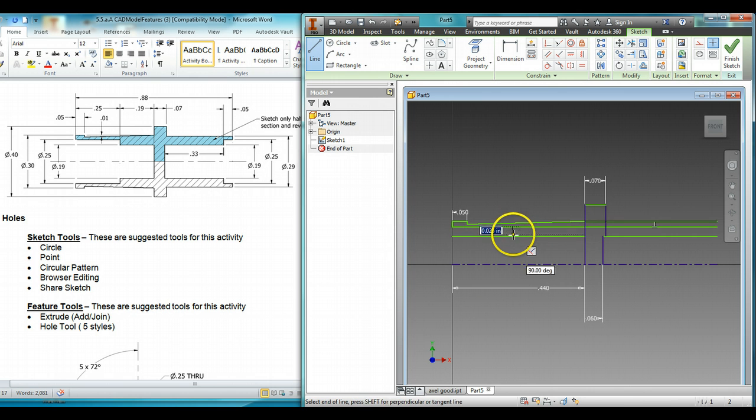Okay, so I have a feature which is 0.25 inches over at the 0.19 diameter mark. So I am going to locate a line right there. Then I'm going to dimension it from the endpoint to the line. So dimension, endpoint, line, and it is 0.25. So I'm going to change that to 0.25. And if that happens, which it does quite often, the dimension that you're trying to do is incorrect. What it did was actually extend the line, and I don't want to do that. So instead of dimensioning it to this endpoint, let me try dimensioning it to that endpoint.